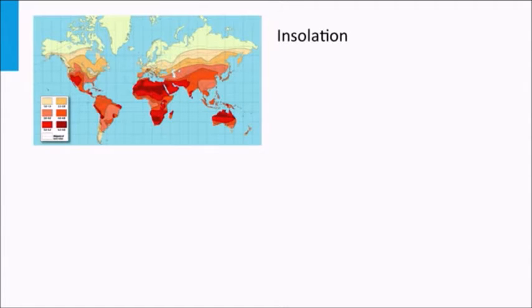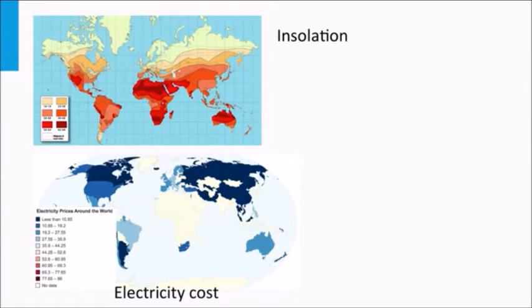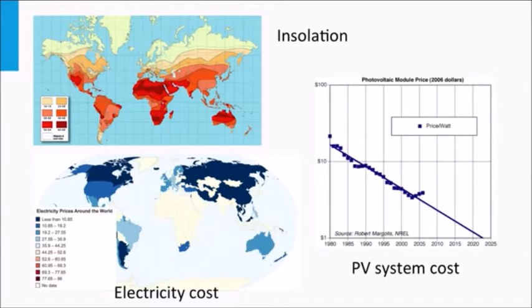Note that the payback period depends on the location of implementation of the PV system. Of course, the sunnier the location, the greater the PV yield and the faster the payback. Also, the savings by the PV system not only depends on PV yield, but also the grid electricity costs. Finally, the initial PV system costs are also a major factor in deciding the payback period.